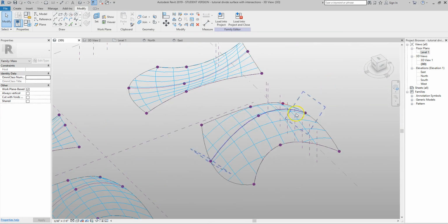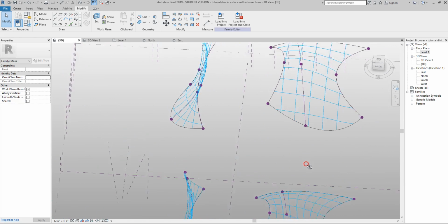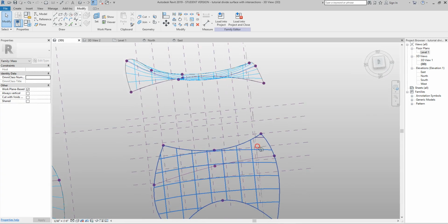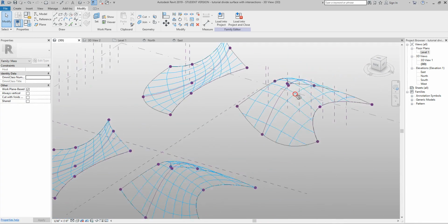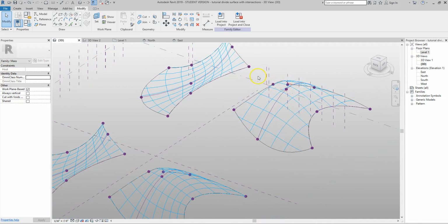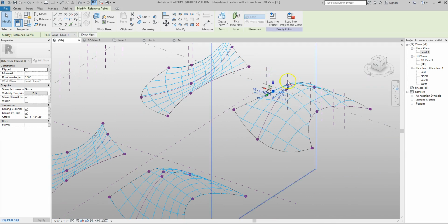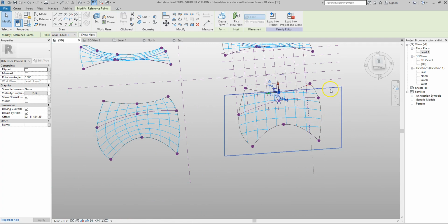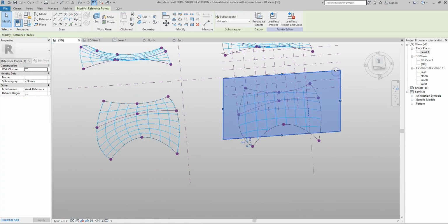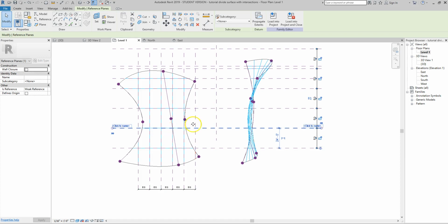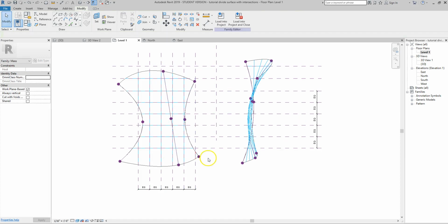And all of a sudden I'm getting the grid shell over it, but actually a projected grid shell. Really useful if you're wanting certain walls or beams to line up on things. Still getting the surface I want, I can still come back in and grab one of my points that was controlling and adjust everything. What's actually really useful too, watch this, I can grab this plane and move it, and it will adjust everything for it.